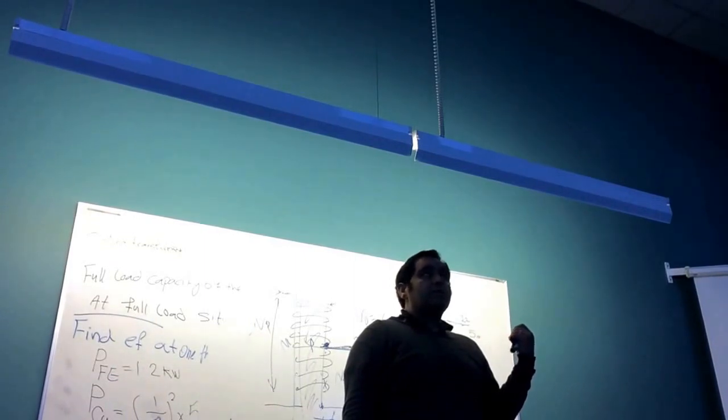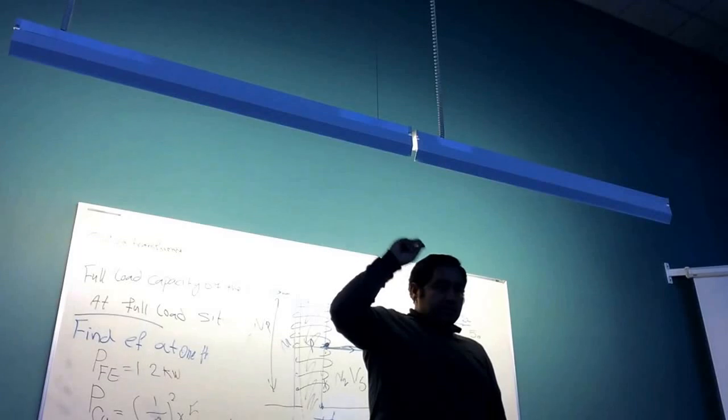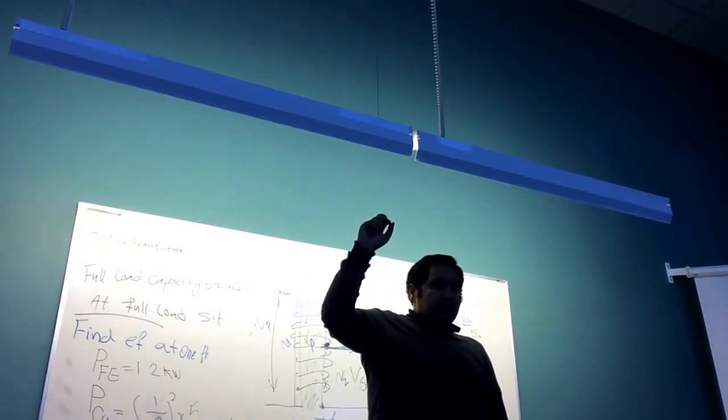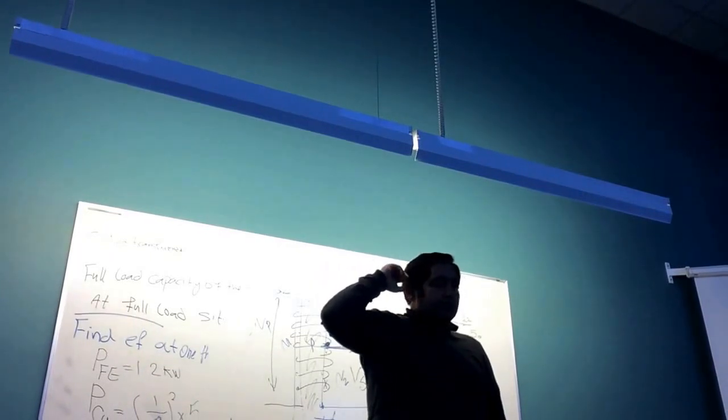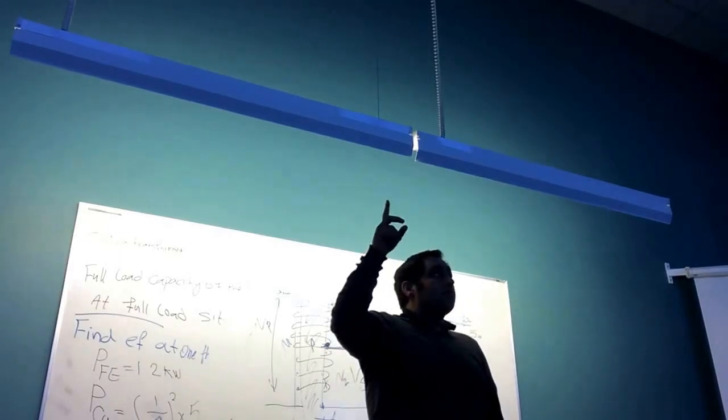You are going to make a problem for other loads. David explained that last time in the last class. He said that if you use direct online for your motors, what's going to happen? You're getting too much current, and getting too much current is going to make a problem in other loads.